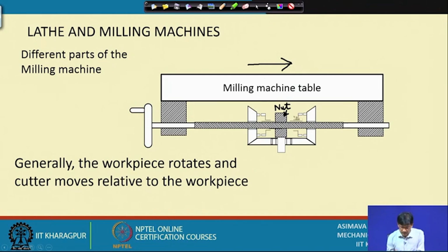Then what are these two things doing? These are called clutches. Okay. What they do is, if they move this way, they connect up with this particular bevel gear 1. Let us name it 1 and let us name it 2, and this one 3. So, if 3 is rotating this way, that means it is moving this way. So, this bevel gear moves this way and that bevel gear moves that way.